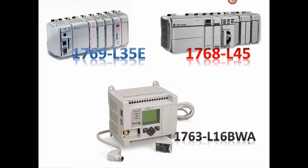The one down below is supported by RSLogix 500, a completely different programming software than the one above, although all three of these are Ethernet. So in that sense, they are very compatible. If you have two controllers from the same manufacturer, but they're not the same platform, then it behooves that single manufacturer to provide you with the interfaces, both any required adapters and the necessary protocols.